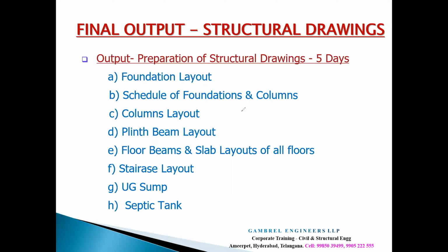So why I'm saying this is, you will definitely take a significant amount of time as we do not have basic knowledge or enough knowledge on the key area or key procedure, which is originally the same for every building. If you are given the design of a 2 floors building, the procedure will remain the same. If we are given a 5 floors building, the procedure would remain the same, unless there are limited changes in it. So you might only need to add dead load and live load for a 2 floors building, maybe even for a 5 floors building if it is not located in seismic zones.